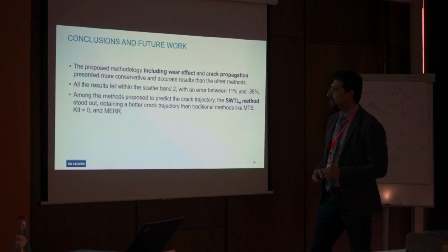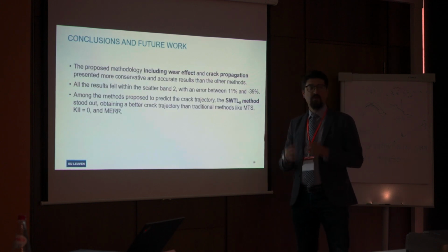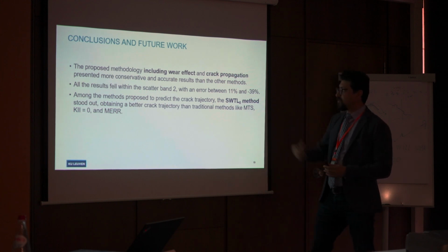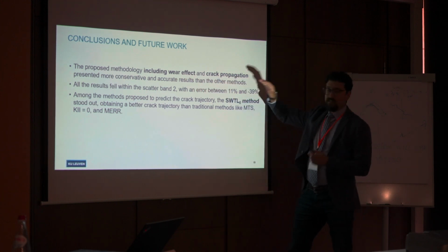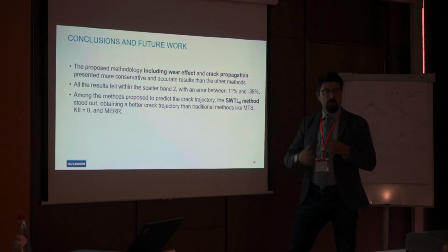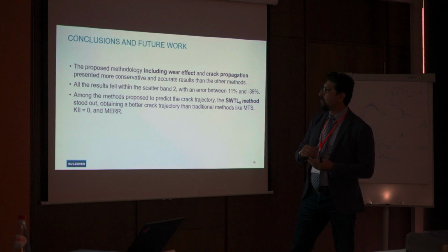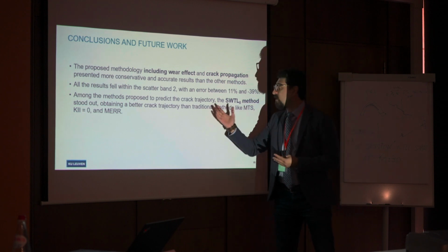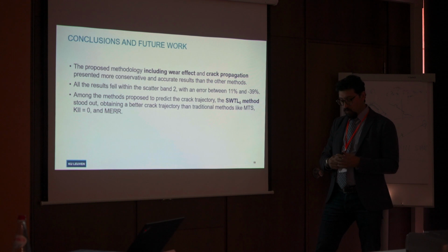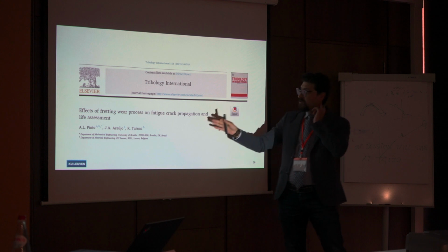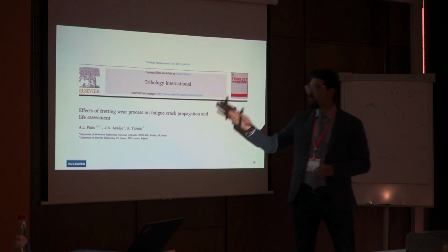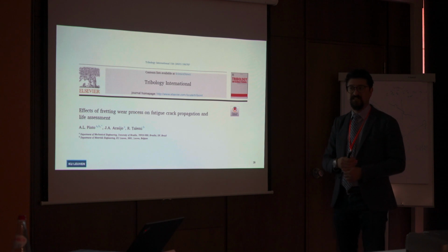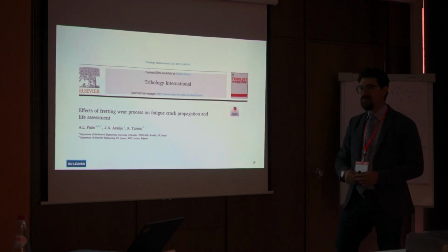I think that's a short summary of part of André's PhD. We tried to include the wear process in crack initiation and crack propagation. We could propose a new criterion which takes into account the effect of non-proportional stressing for crack propagation, and he also tried to validate that, and it worked. I think that's it from my side. This result was published last year, so if you're interested, you can take a look at our publication. I don't know if I am on time or not.